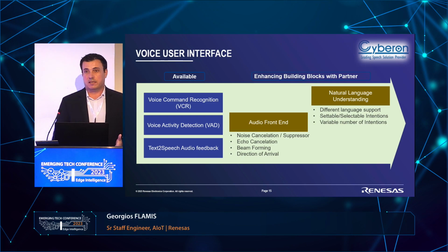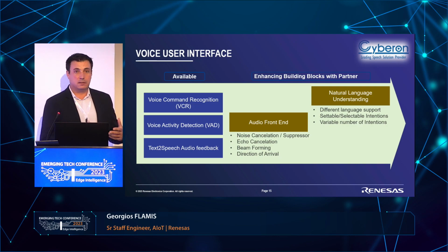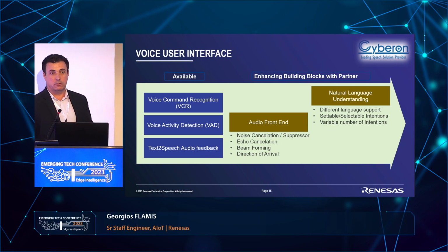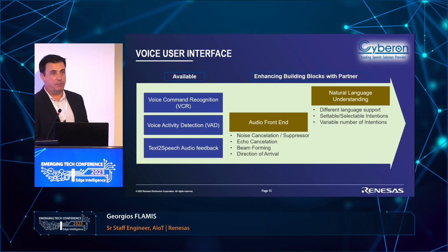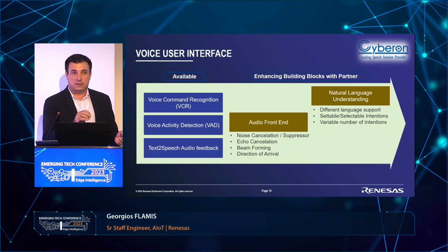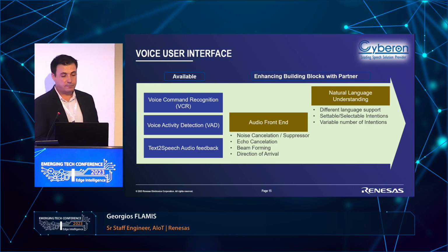and voice activity detection technology that allows the device to wake up when there is voice coming into the system. By using that, we can control and reduce the overall power of the system, because when there is no reason for the device to operate or to make recognition, it just goes to sleep. And when voice appears, it will wake up. Consider that the device we're talking about runs at 48 megahertz, so a small system can still wake up and recognize the voice, recognize the word that has been sent.